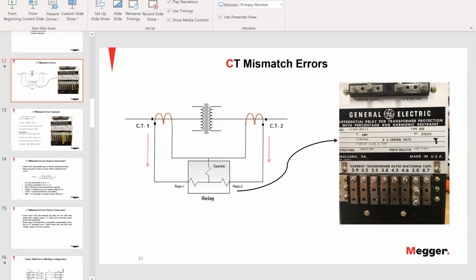That's a type of protection that is used on a lot of systems, that prevents the successful culmination of a closing operation when the relay or the protection system detects that the switching is being done and a fault is present in the system. There are several implementations of that protection function. I guess that should answer the question.